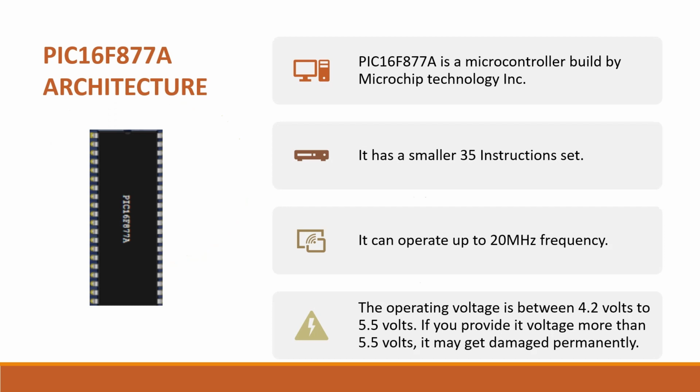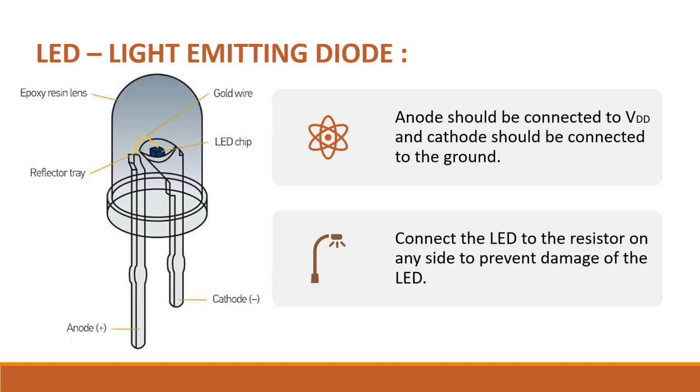This is the PIC16F877A architecture. This microcontroller is used in this project. It is basically built by Microchip Technology. It has 35 instruction sets. It operates at 20 megahertz frequency. Its operating voltage is 4.2 volts to 5.5 volts.